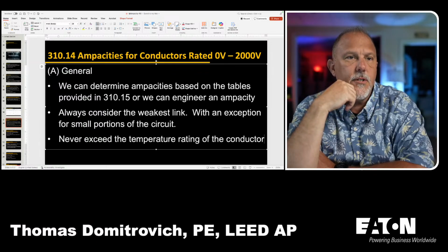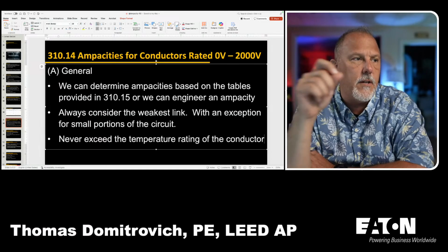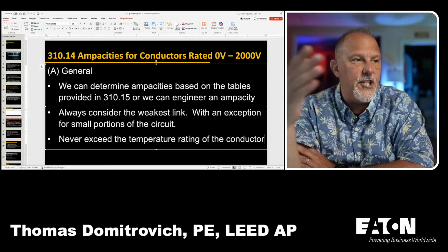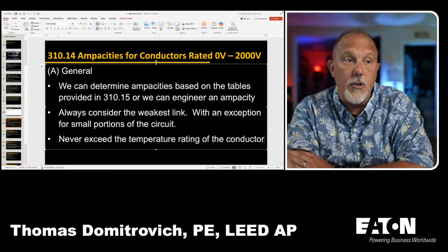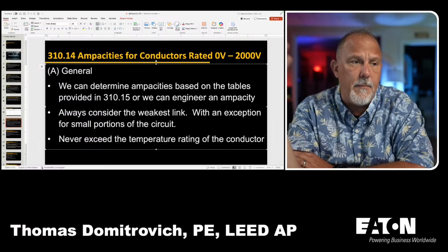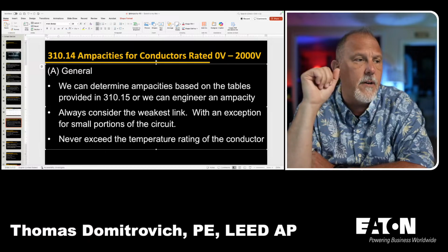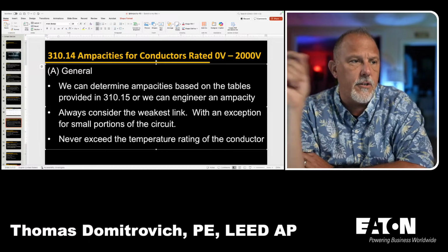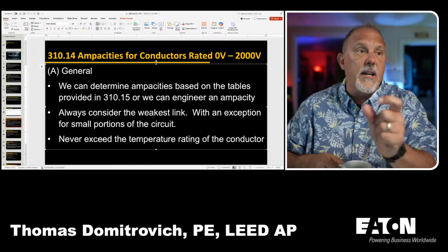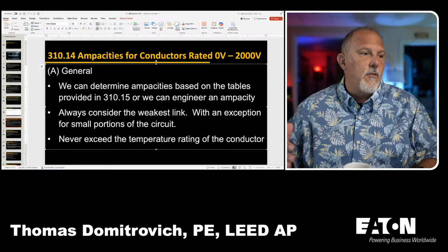The ampacity tables, the principal determinants of operating temperature are as follows. Ambient temperature may vary along the conductor length. Heat generated internally in the conductor as a result of load current flow. The rate at which generated heat dissipates into the ambient medium. That's if you have insulation that covers it, etc. And then adjacent load-carrying conductors. Adjacent conductors have a dual effect of raising the ambient temperature. So you need separation. In fact, there is a thing for that. So that's in the general requirements.